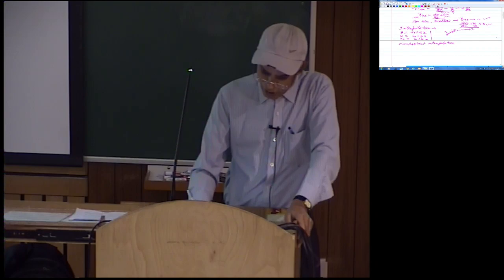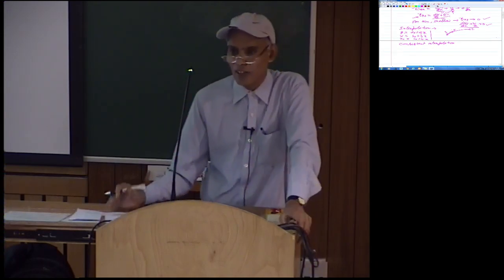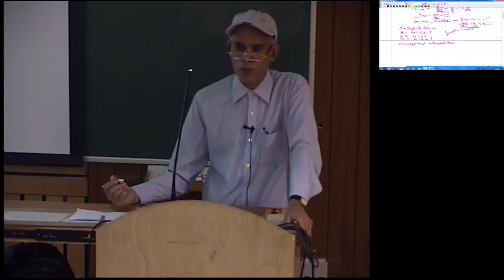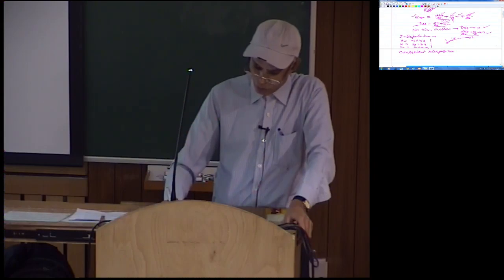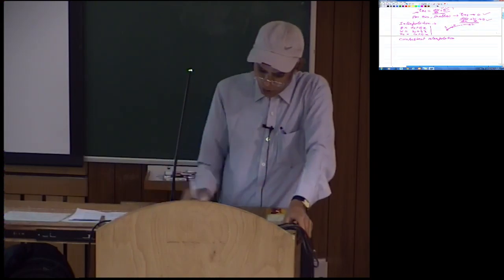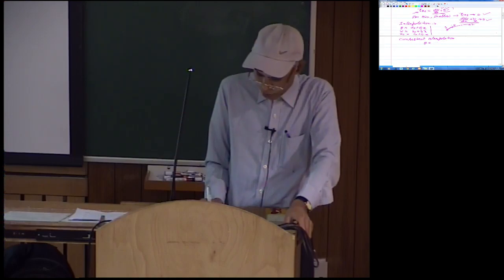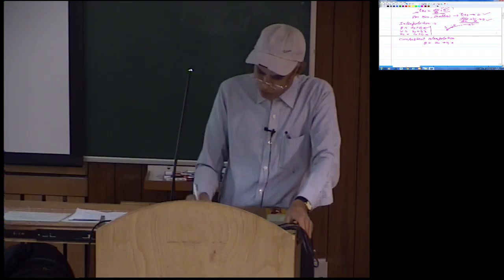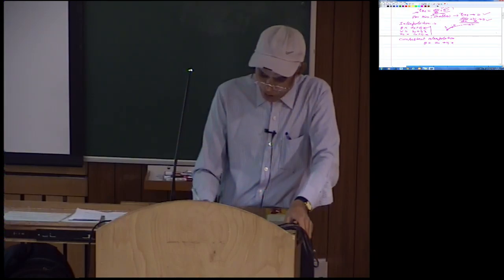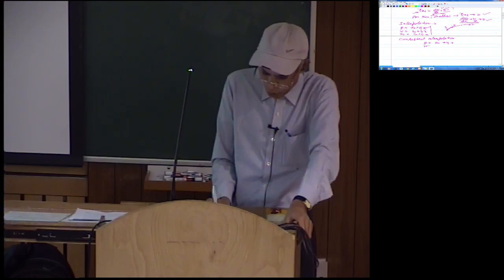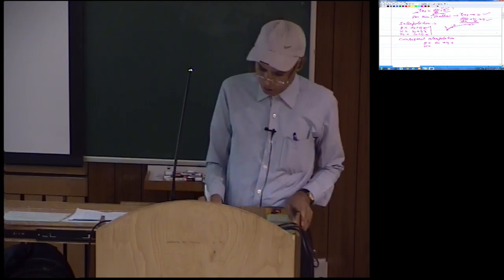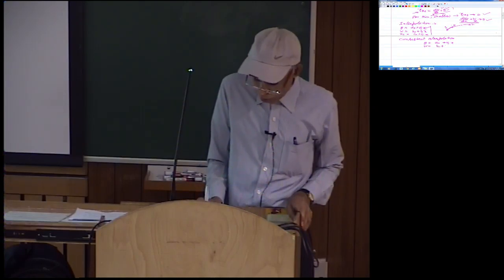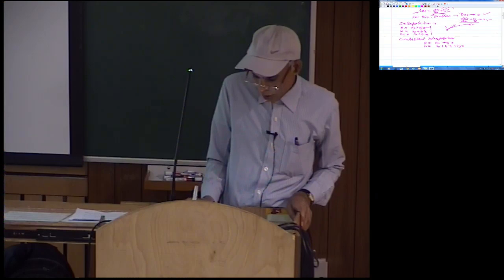So if theta is linear here, which is minimum, we cannot take less than that. Constant theta is not acceptable, because then its first derivative will not exist, which is required in the strain and therefore in the strain energy expression. So the minimum is that theta must be at least linear, like what I just wrote, a0 plus a1x. Since w appears in gamma xz as a first derivative, w must be quadratic, so that dw by dx and theta are consistent. So w should be b0 plus b1x plus b2x square.